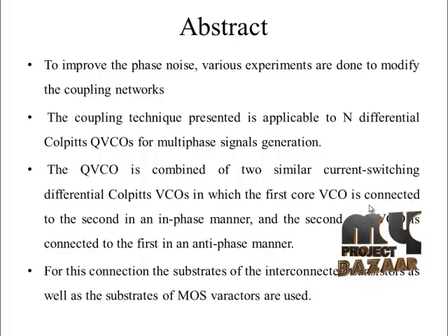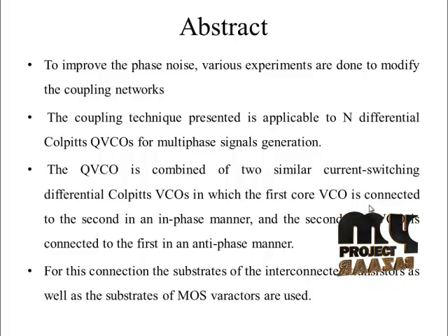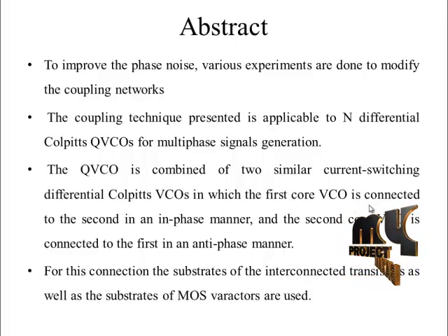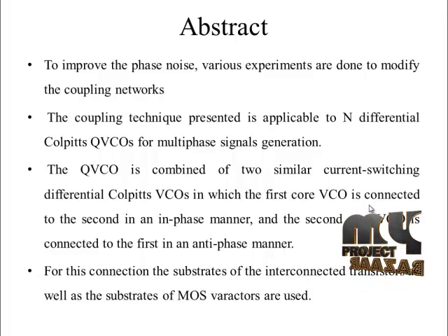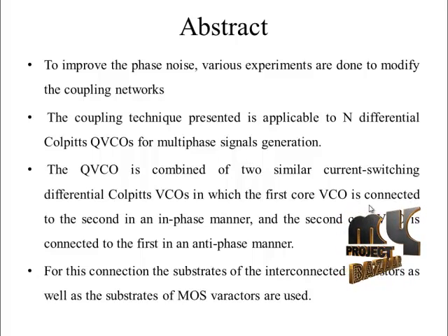In conventional cross-connected LC VCOs, the noise generated by the active components perturbs the VCO output at its zero crossing, that is the maximum noise sensitivity point. On the other hand, in Colpitts oscillators, the maximum noise level, that is the maximum of the impulse sensitivity function generated by the core transistor, is aligned with the minimum oscillator sensitivity point. Thus, Colpitts oscillators have superior cyclostationary noise properties and, as such, potentially a better phase noise performance compared to the